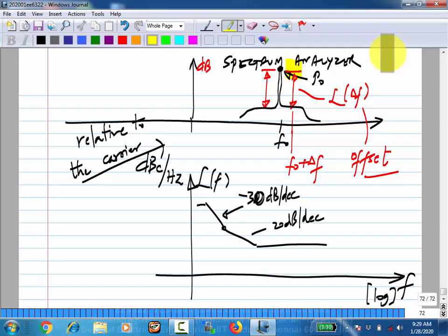These definitions again you have to know, because you want to know how much jitter there is eventually, right? The jitter variance determines the bit error also. Or you have to make sure that your bit period is longer than a certain value, which depends on the jitter variance. Otherwise you will get too many errors. So to calculate the jitter variance, you have to be able to find the spectral density of this phase noise and get the jitter variance.